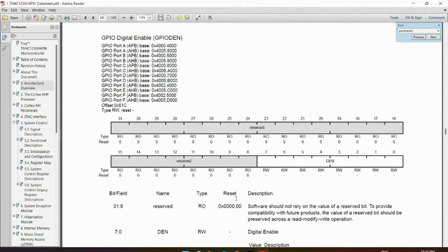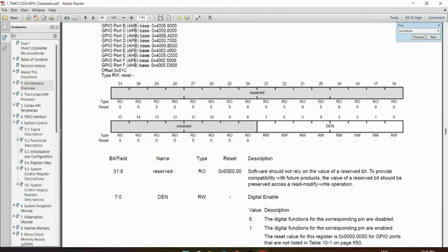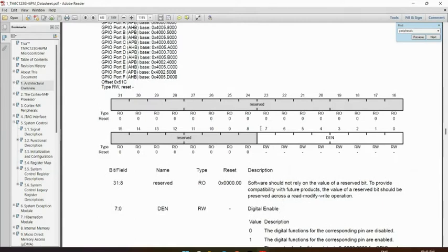So which bit do you have to make 1? We have to make LED 1. The red LED is at pin number 1. Port F pin number 1 is the red LED. So all these registers are helping you to go to that particular pin only.